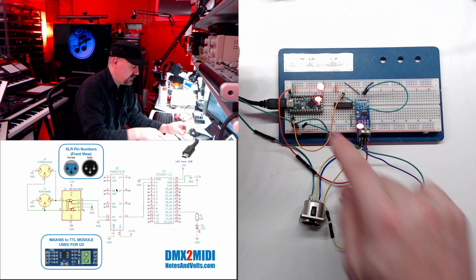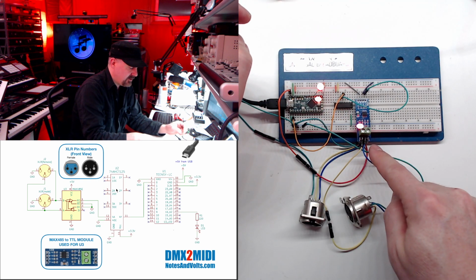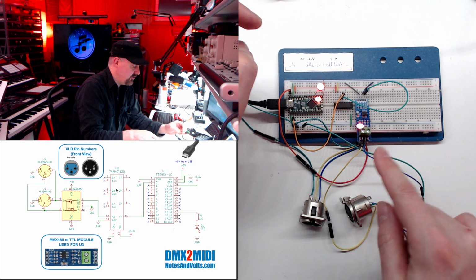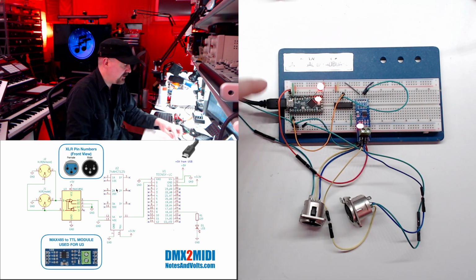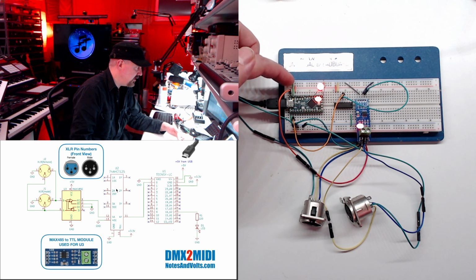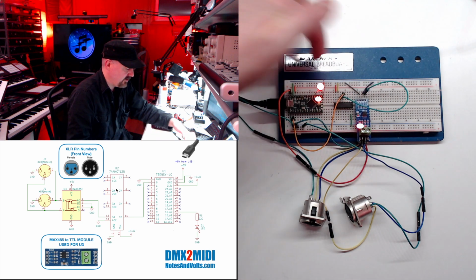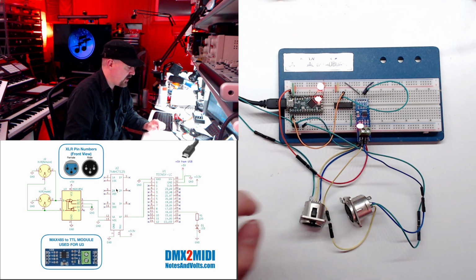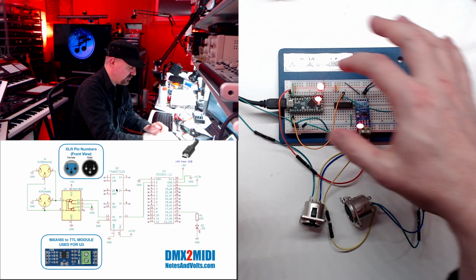It's okay. So we've got our 5 volts going to our module. Our ground is going to go to any ground from our Teensy. So what I did is I ran the ground pins, one up to this strip here and the other one to the blue strip at the bottom. So both of these strips are now grounded.